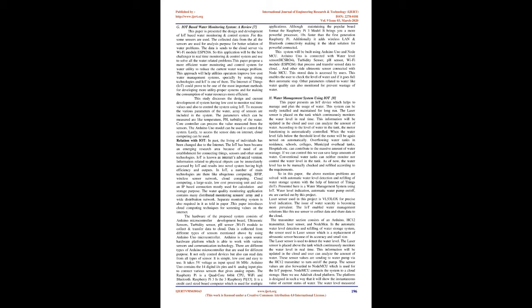The system runs on battery power and comprises 4 sub-circuits working synchronously: sensor circuit, controller circuit, SMS circuit, and relay driver circuit. The sensor senses the level of the water in the tank, which is continuously fed to the controller system. As the system encounters the empty level condition, the status of load shedding is checked. The relay coil is energized and the pump operates when there is no load shedding.